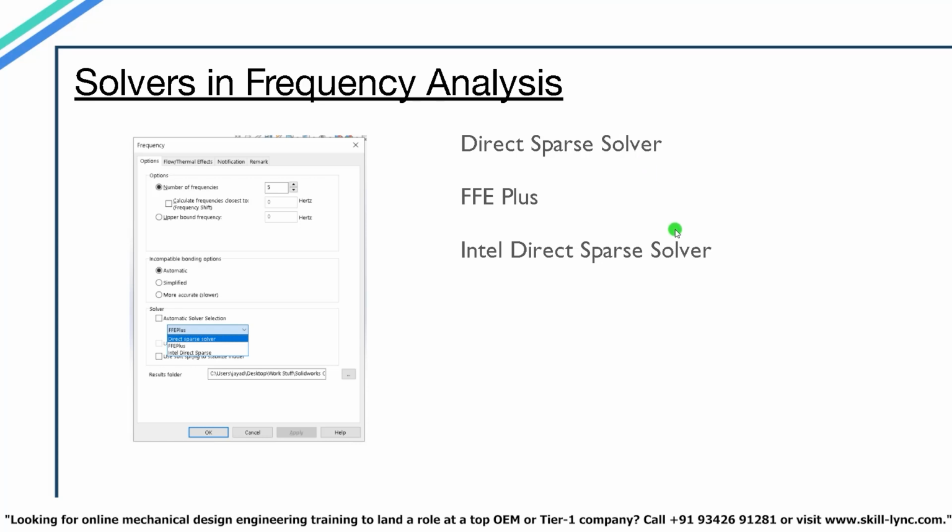When the moduli of elasticity of the materials used in the model are very different, let's say in the same model you have two different materials, for example steel and nylon, then iterative methods could be less accurate than direct methods. In such scenarios, direct solvers are recommended. When performing analysis where there are no interpenetration contacts and bonded contacts, direct solvers tend to solve these much faster.